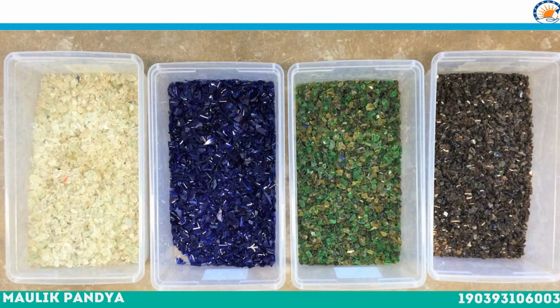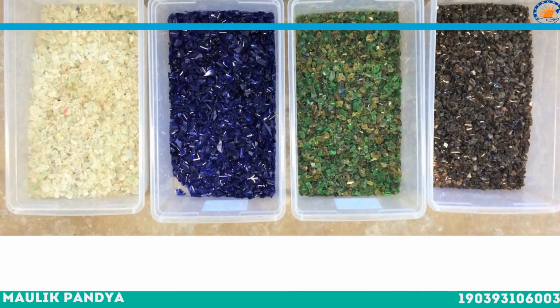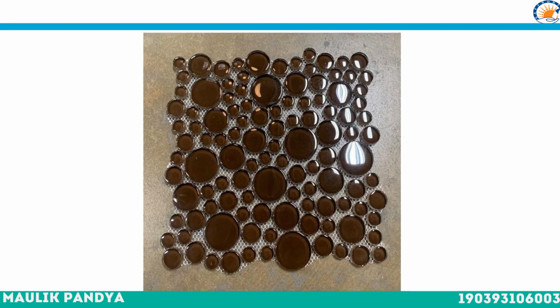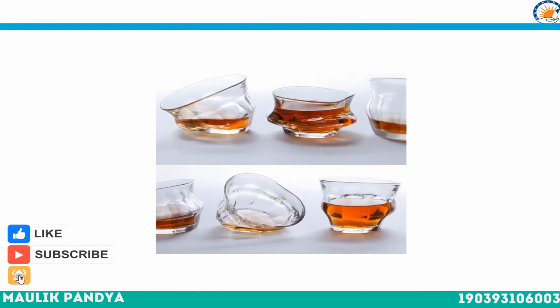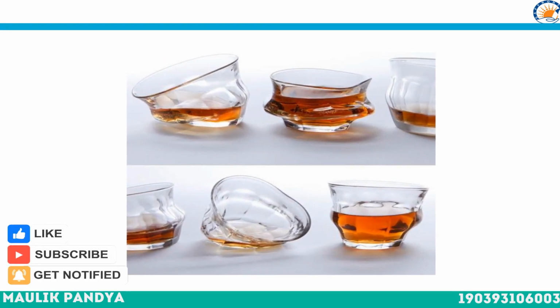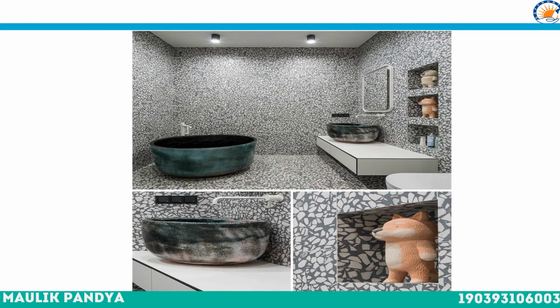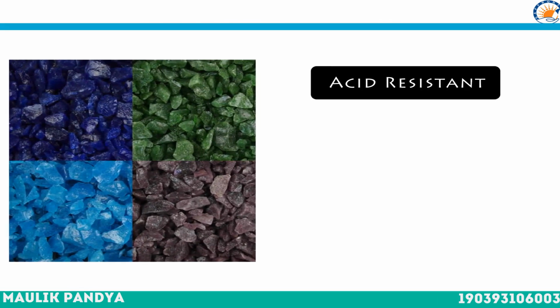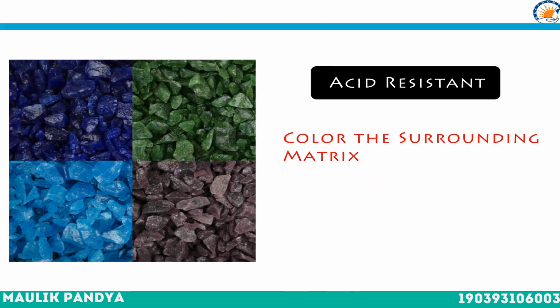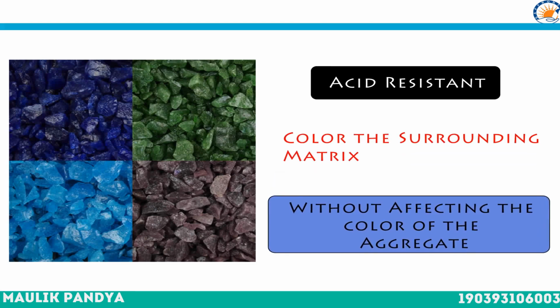In general, lighter colors of glass are used in darker matrices, and vice versa. But not always. A dark brown glass in a dark brown matrix can have an appeal all its own. Mixing light and dark colors of glass will give you a terrazzo effect. If you use clear glass aggregate, it will take on the color of the matrix, and it will add the most depth.